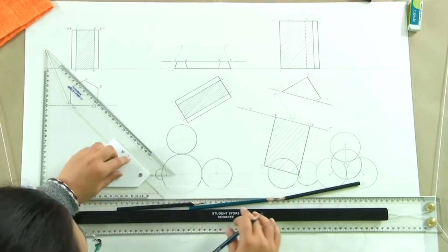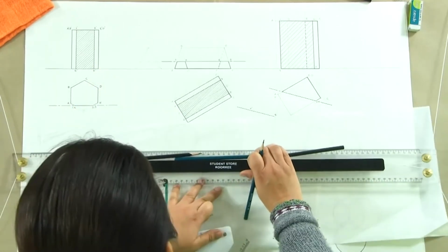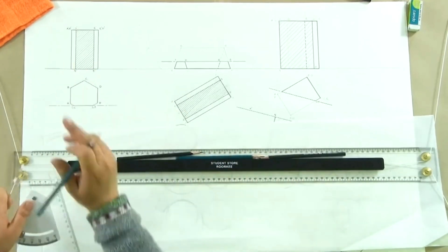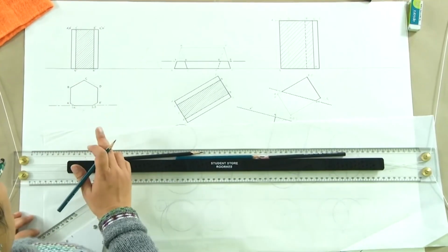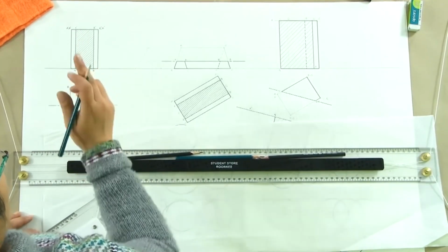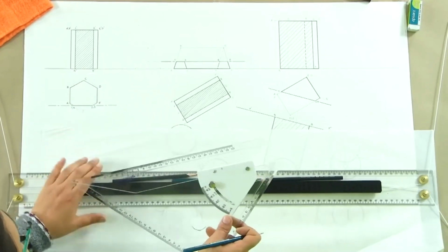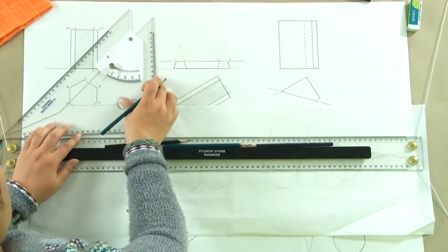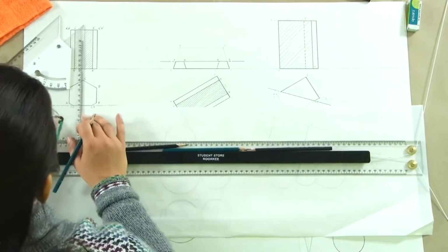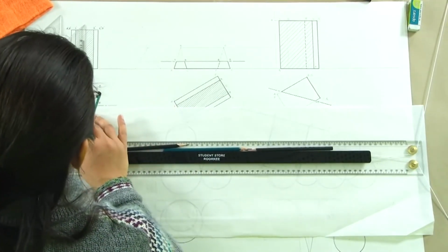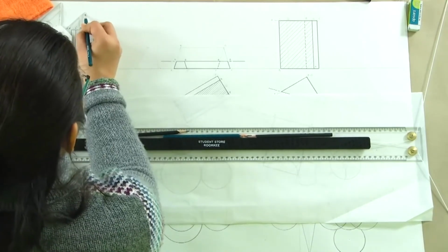Now, assume that this particular problem which we had taken earlier, now instead of this, suppose this section plane was actually inclined to HP and perpendicular to VP. So, what if I have a section plane which cuts this prism? This is the axis here. I will draw an axis here first.